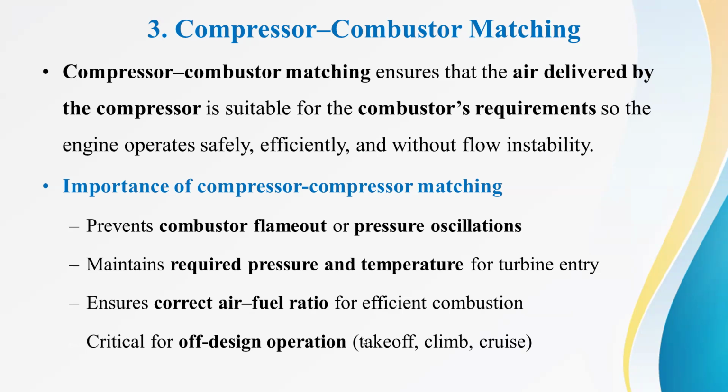Then heating will take place. So they are adjacent components. Therefore, they need to match each other in order to ensure stable and efficient flow. So compressor combustor matching ensures the air delivered by the compressor is suitable for the combustor's requirement, so that the engine operates safely, efficiently, and without flow instability.